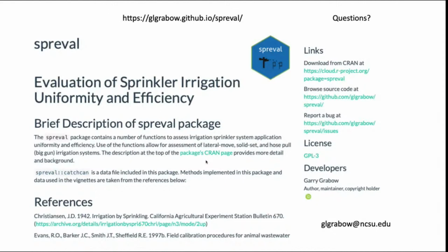Usually if you get it from municipal supply, it's going to be expensive, of course, at least here in the United States, but it'll be clean. But when you go to drip, you definitely want to filter it. And then the next issue on subsurface drip is how close you space the laterals. And I think from what I recall in turf, you probably don't want to space the laterals much more than, well, a foot would be 30 centimeters, 30 to 45 centimeters apart, because that way you assure you have a decent lateral distribution.